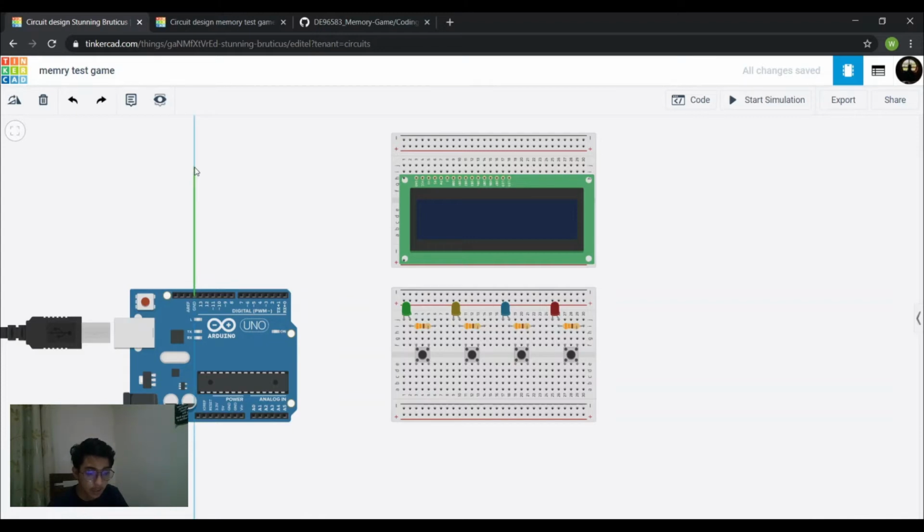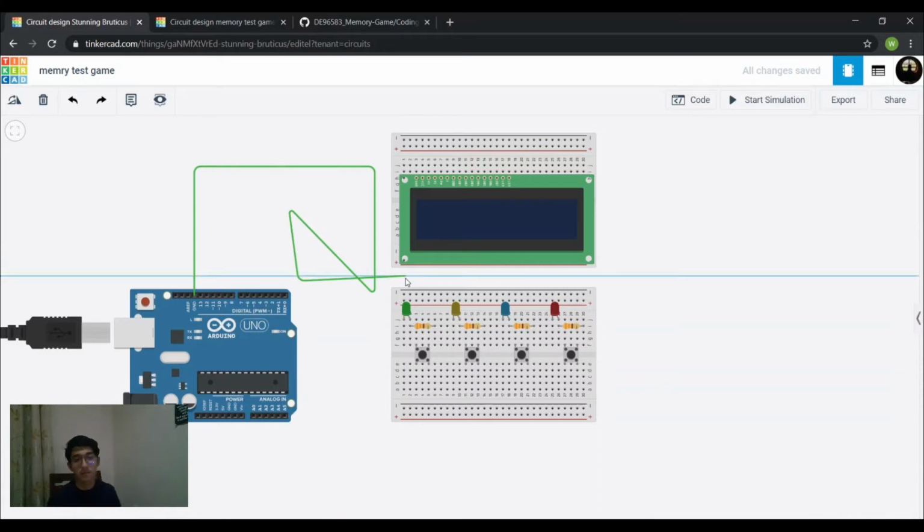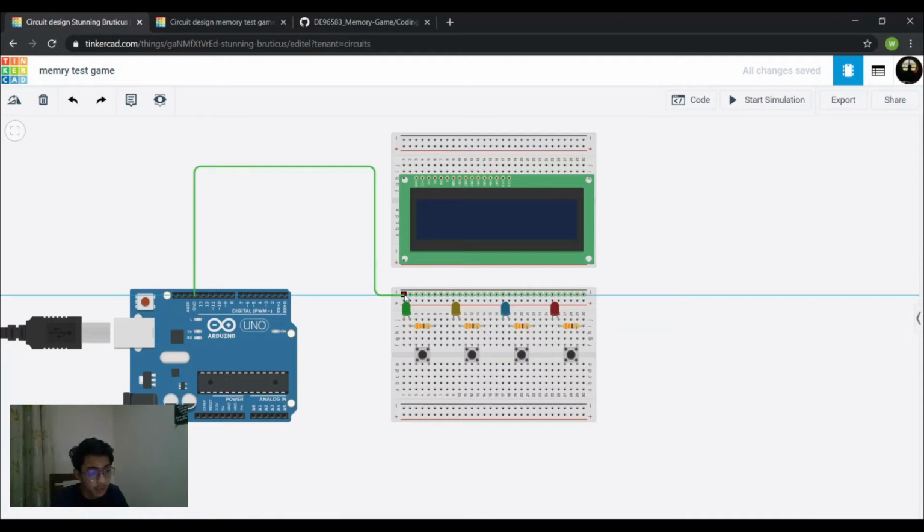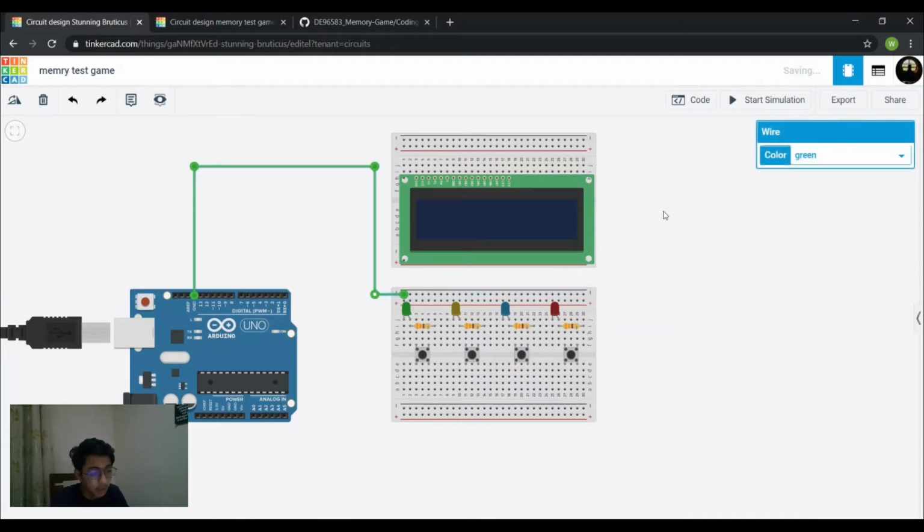If you can see, if I move it upwards, you can see the blue line, which means the wire is straight from the component. So make it straight, make sure they have the blue line, then pull it down, and then just pair it to the component. Or maybe, for example, you click here, then you can see once you click, your wire can be moved. You can also just press backspace if you mispush the button on your mouse, and then just put it on the component.